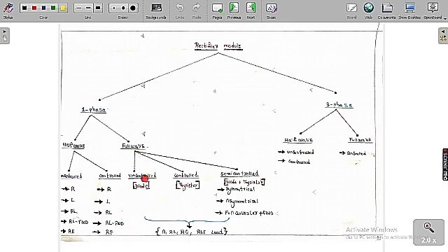And for full wave, we are going to study the uncontrolled, where we keep only the diode, the controlled, where we keep only thyristors, and the semi-controlled, where we keep both the diode and also thyristor. In this semi-controlled section, we are also going to study the symmetrical, asymmetrical and full converter plus freewheeling diode. And for each of them we are going to vary R load, RL load, RE load and RLE load. For all these loads, we are going to see the variations of the current, voltage and each and everything.